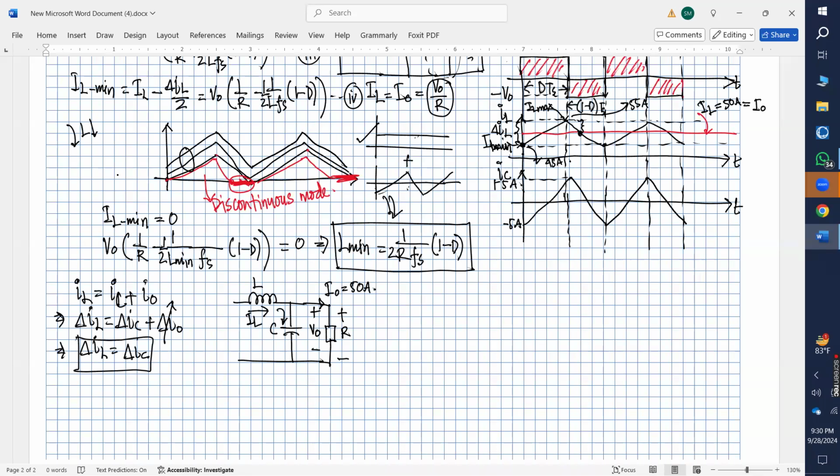So whenever your inductor current is 45 amps, 5 amps is going in the opposite direction. That's why this is negative, to make this current 50 amps, right? But whenever your inductor current is above this average value, suppose this is 55 and your load current is 50, then you can have 5 amps in this direction, which is your positive current.